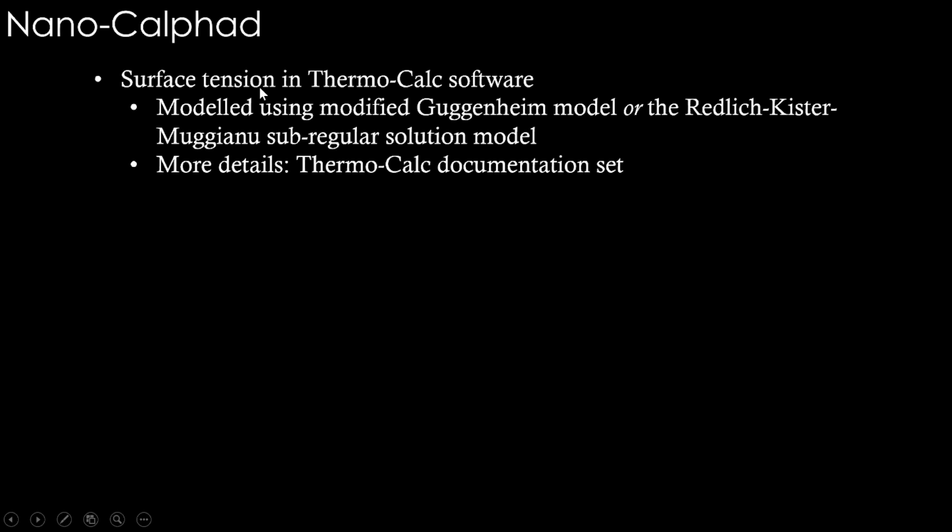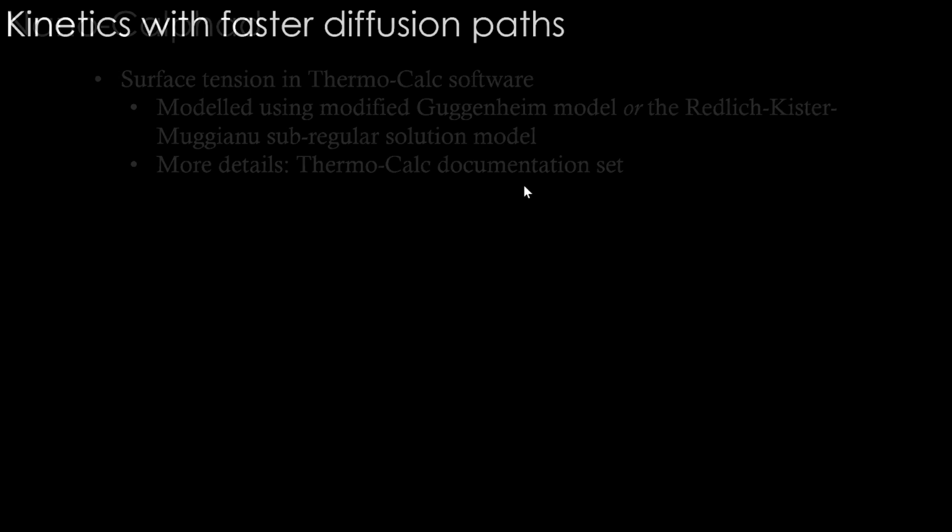How about this surface tension in Thermo-Calc software? In Thermo-Calc software, this is there as a property modeled using the modified Guggenheim model or the Redlich-Kister-Muggianu subregular solution model. More details are there in the documentation set, you may explore. And that's about the nano CALPHAD.